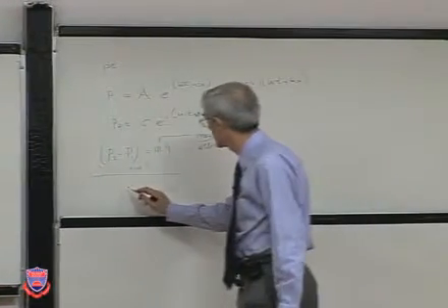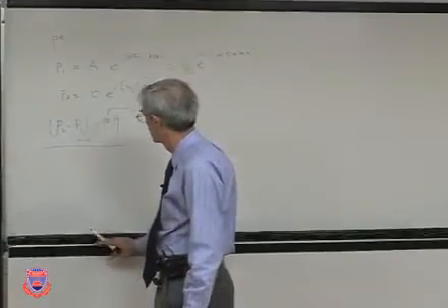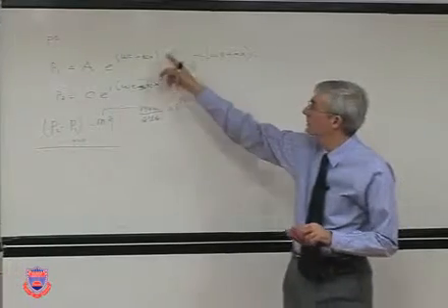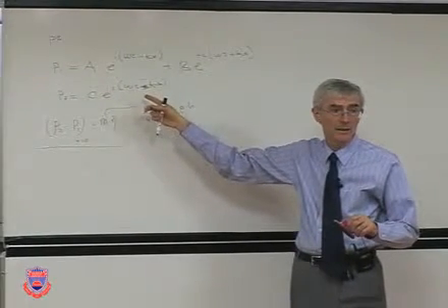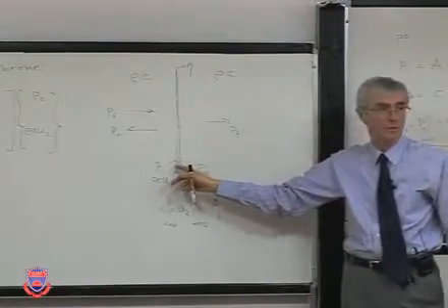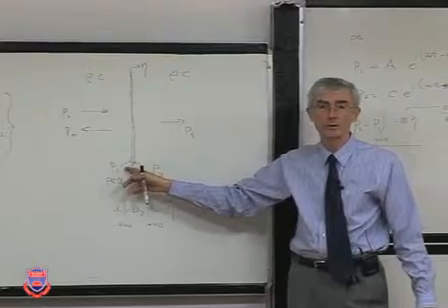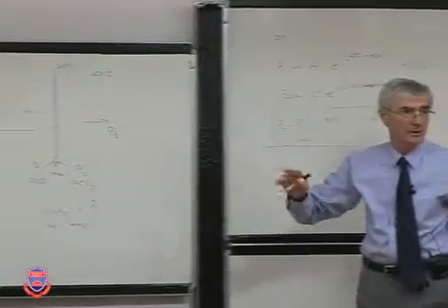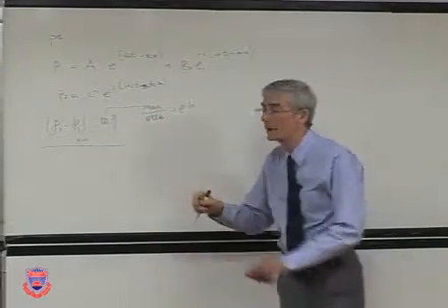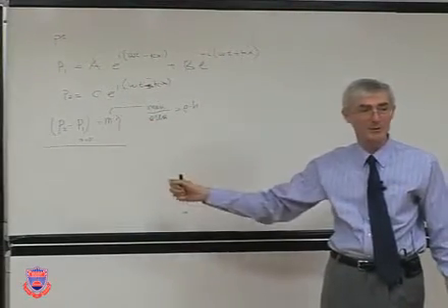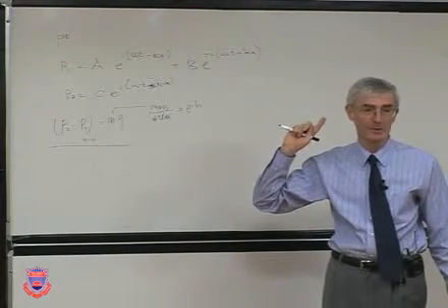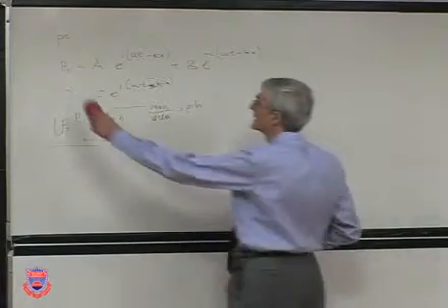So if we go back, and let's see. You can see now that we don't necessarily need these distributions, because we're always working right at the surface, and we're interested in total pressure on one side and total pressure on the other side, irrespective of what's reflected, what's incident, and so on. And we can find those once we have the transmission matrix, because we know what they should be in terms of the transmission matrix elements.